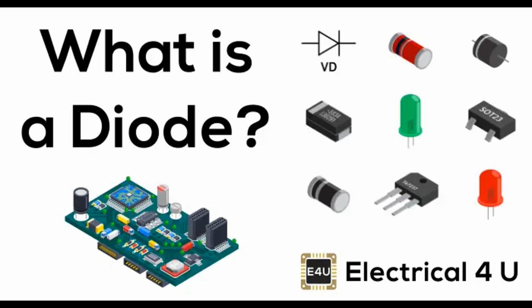Protection against reverse current. In systems where backflow of current is not allowed, e.g., in solar panels or batteries, blocking diodes are used to prevent reverse current flow when there's a voltage differential in the opposite direction. Circuit isolation. Isolation diodes are used to prevent feedback into a circuit. They isolate one part of the circuit from another, which is especially useful in power supply designs.